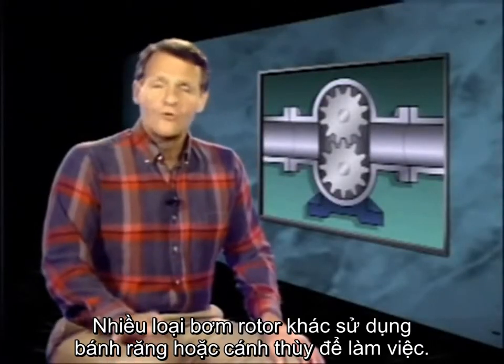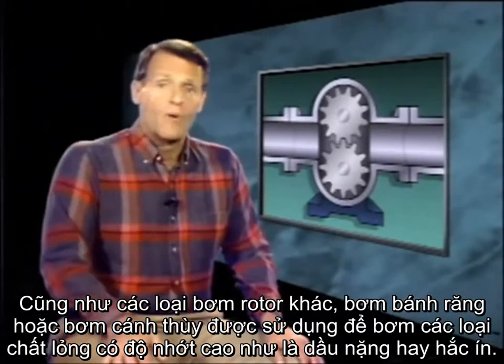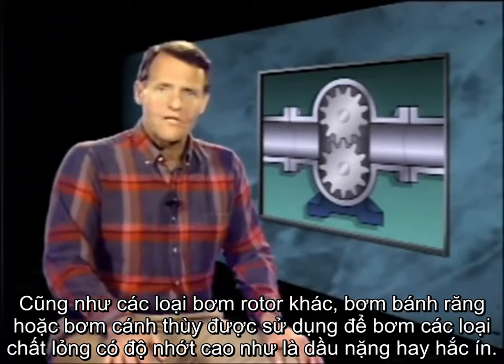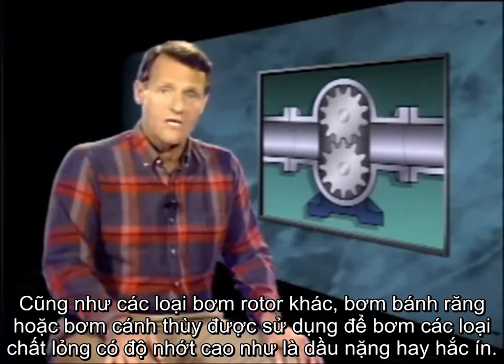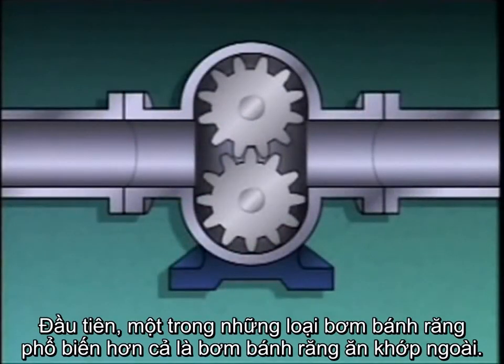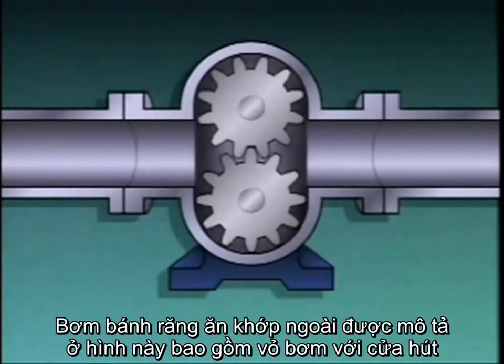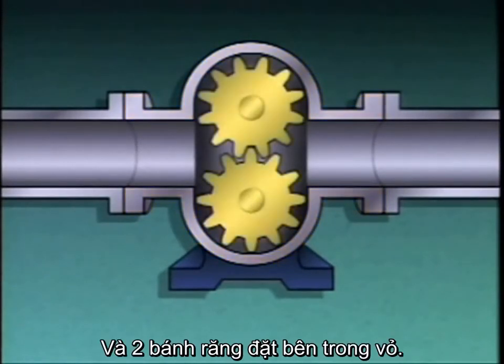Many rotary pumps use gears or lobes to move processed liquid. Like other rotary pumps, gear pumps and lobe pumps can be used to move viscous liquids, such as heavy fuel oils and tars. Let's look at gear pumps first. One of the more common types of gear pumps is an external gear pump. The external gear pump shown in this illustration consists of a casing with a suction port, a discharge port, and two gears located inside the casing.